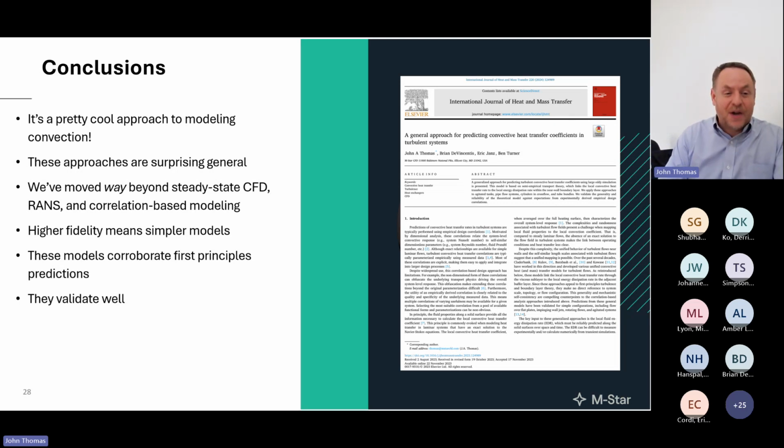It's neat to see it work across a wide range of scales, and it's not totally surprising because the boundary layer hypothesis works across these scales. So it's not surprising to me that this works across scales as well. Likewise, it makes sense to me that all the fluid needs to know in order to exchange thermal energy with the wall is contained inside that small region of fluid. It doesn't need to look over its shoulder to figure out what the Reynolds number of the impeller was. It doesn't need to look down at the bottom to see what type of dish bottom the tank has. We can use this generalized approach to handle a wide variety of systems because we're appealing to the transport physics at the level of the transport carrier.